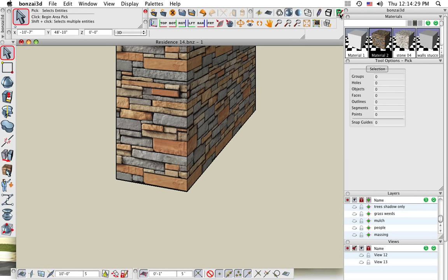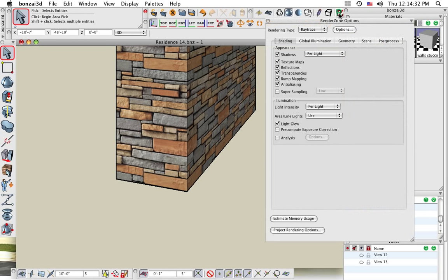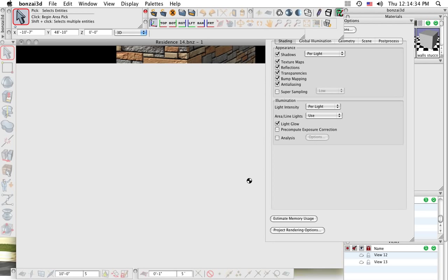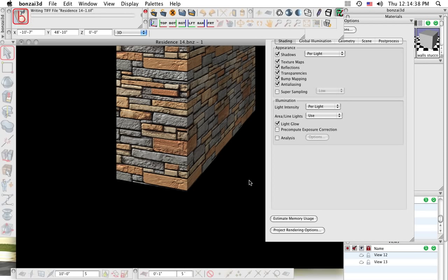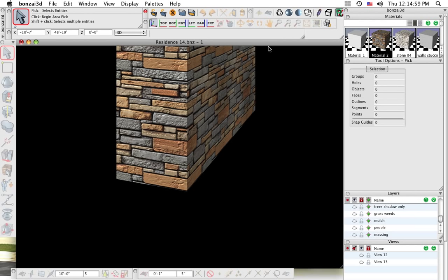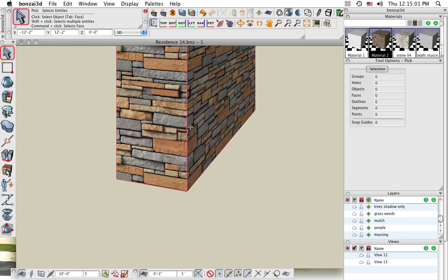But if I were to click on the RenderZone button, so I actually do a RenderZone rendering of it, then you can see we can take advantage of the specular hotspots, we take advantage of the bump shader effects, and so it really takes that 2D flat image and makes it pop as more of a three-dimensional texture on that surface. Okay, and we do get the specular hotspots based on the actual lighting conditions, which is pretty neat. So if I were to change my light, the actual 3D effect would change based on where the actual light is shining from.